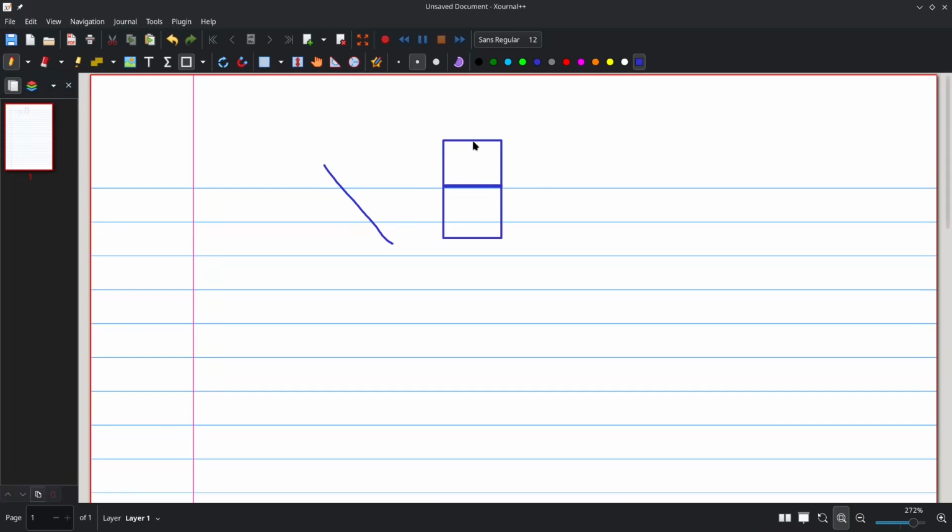If this is for common cathode, for example, this one is A, B, C, D, E, F, G. Understand? Then this one will be grounded for common cathode. When it is 1, it is grounded. That's common for common cathode. So where this one will be grounded, that means all these pins need to be 1 for it to make a connection with the grounded one.